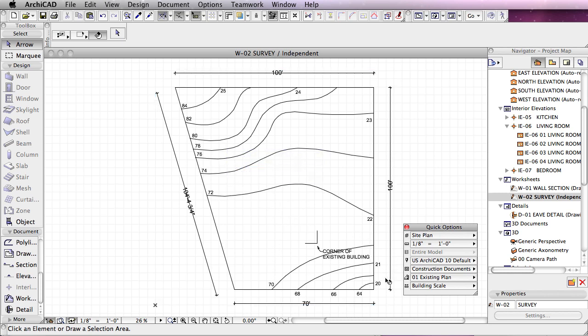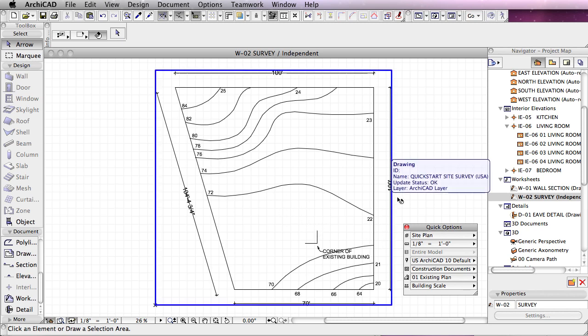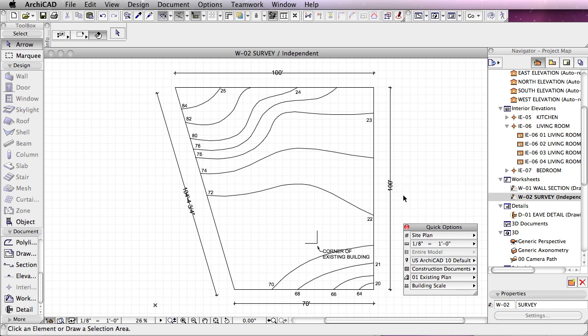If you're working with a metric, I have numbers 20 meters, 21 meters, 22, etc. And so we're going to be putting it in around 22 meters in height above, we could say sea level, or perhaps you're used to calling it something else, like in Australia it's called the Australia Height Datum, or AHD, I believe. So in any event, the first job after bringing it in is to verify that it's the right scale, that it's actually the right size, that it measures properly.